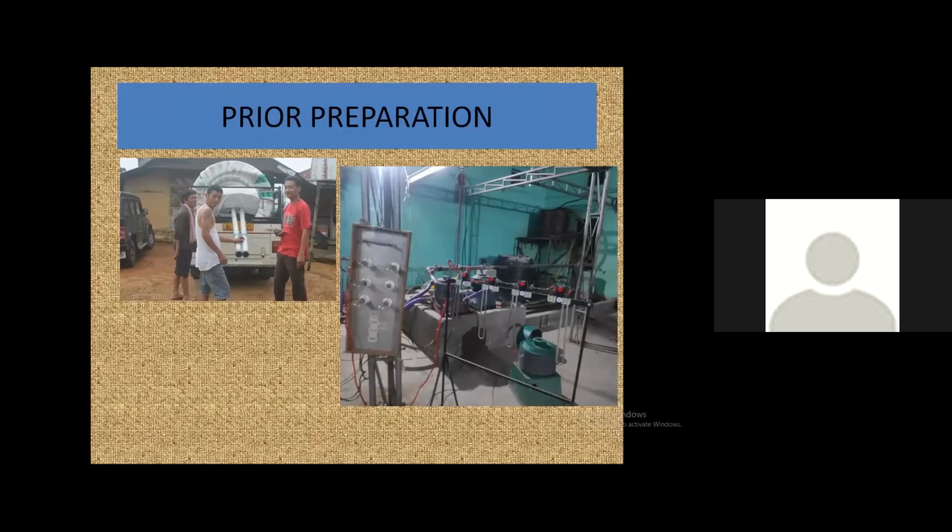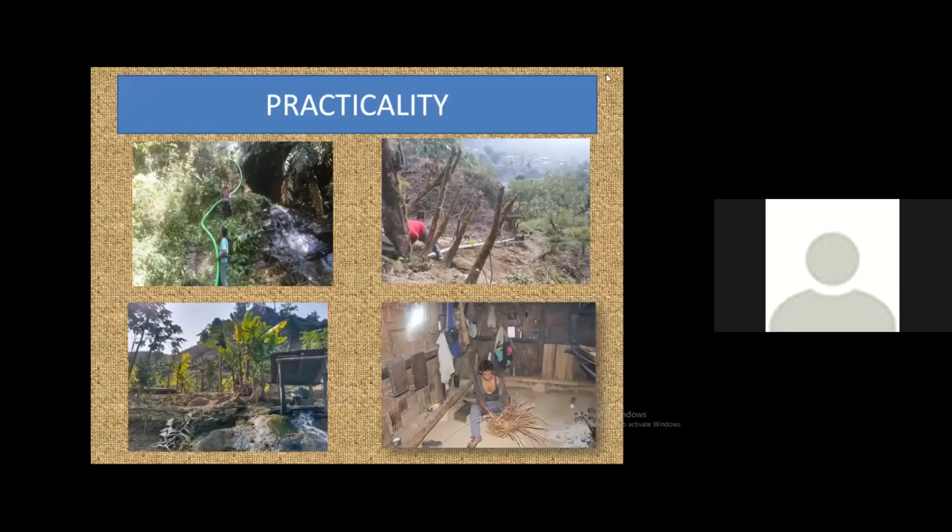The next part would be practicality. We make sure that the sites are practical. If you see on the top, for those who are a bit more technical, that's not the way to put a penstock. But in our case, our machines are quite small, so we focus more on the practical aspects. And out here, we can see that we're using some flexible pipes as penstock.